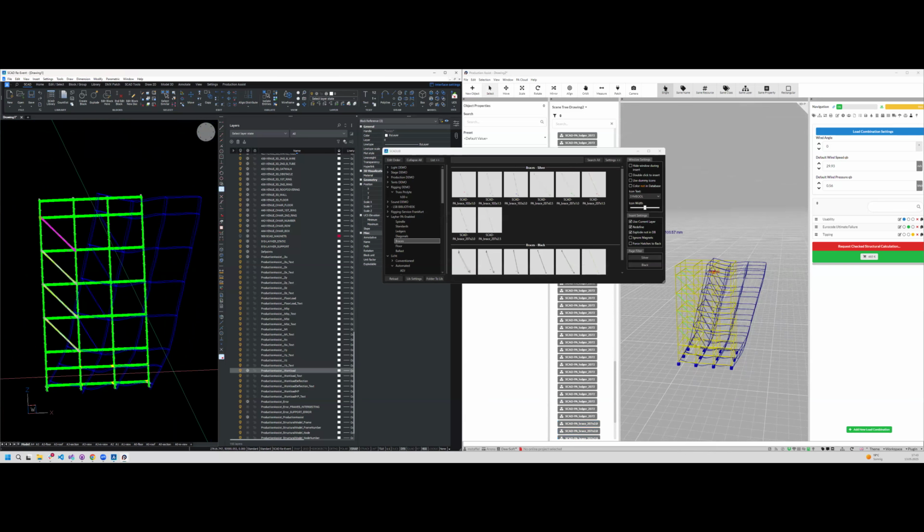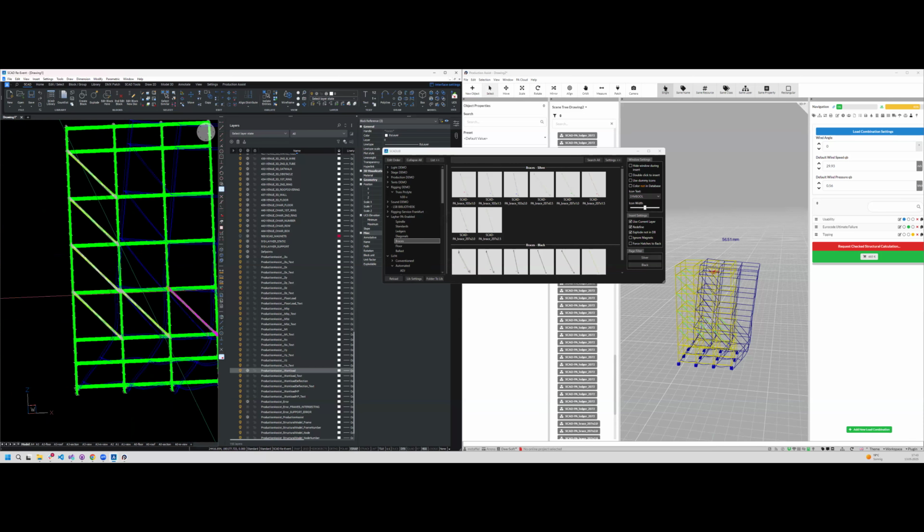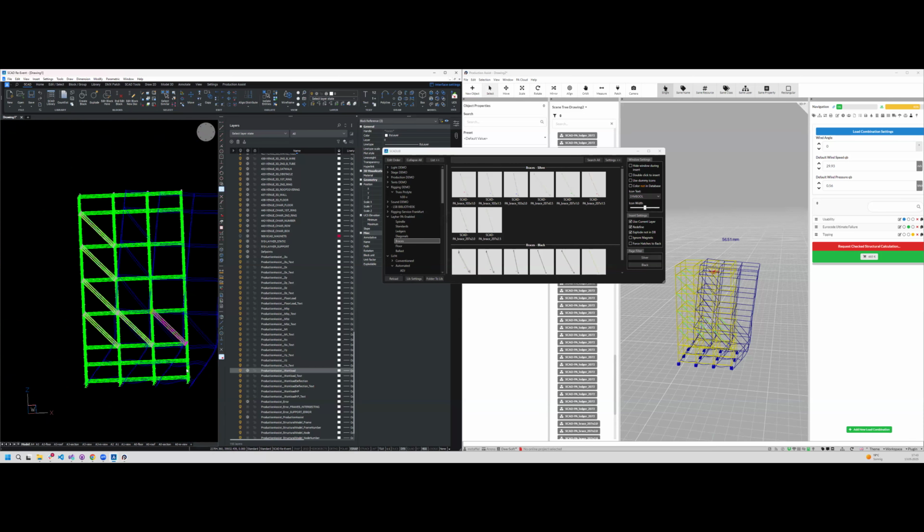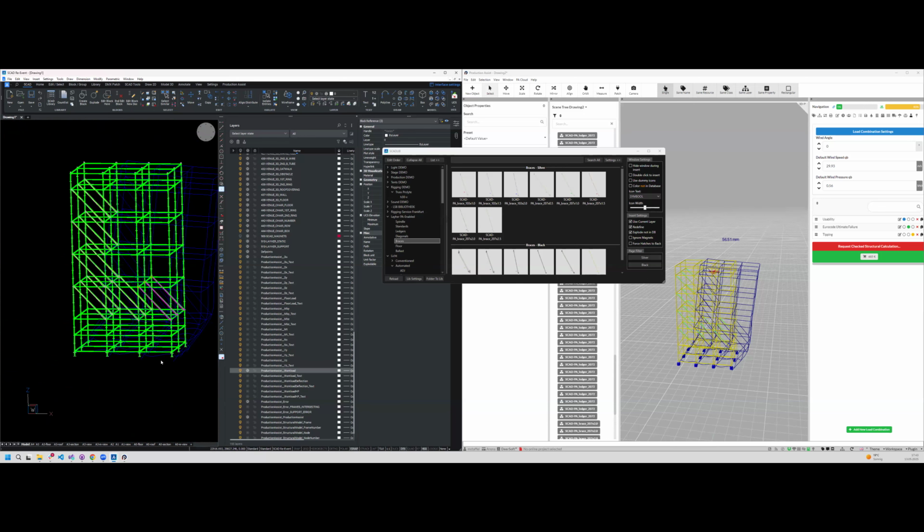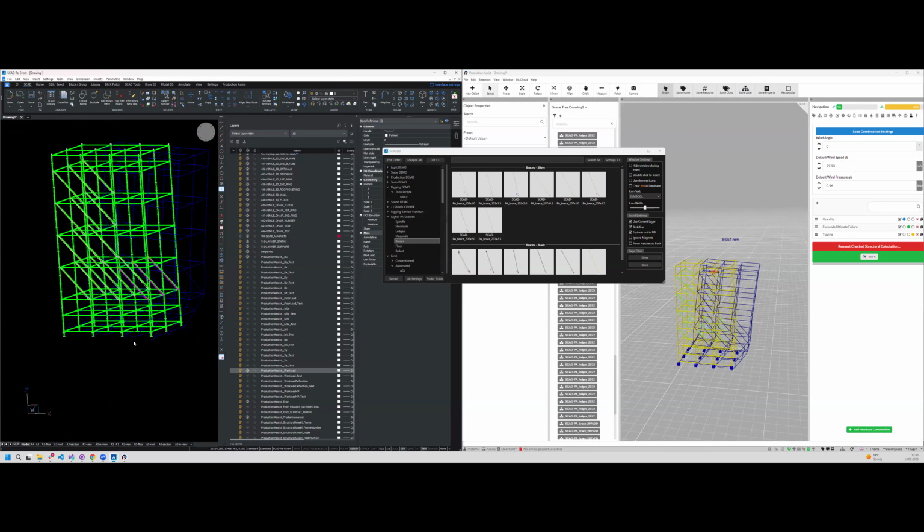For sure, the more of these you're adding, so if I'm now using this and copying it like in here, you will see that this now straightens out the structure. And you really see what diagonals actually bring for the structure. If there's only one diagonal on top of here, you see there is some deflection. If you have 3 of them, it really puts down the deflection. But right now, the main problem in here is that they don't have a bottom one.